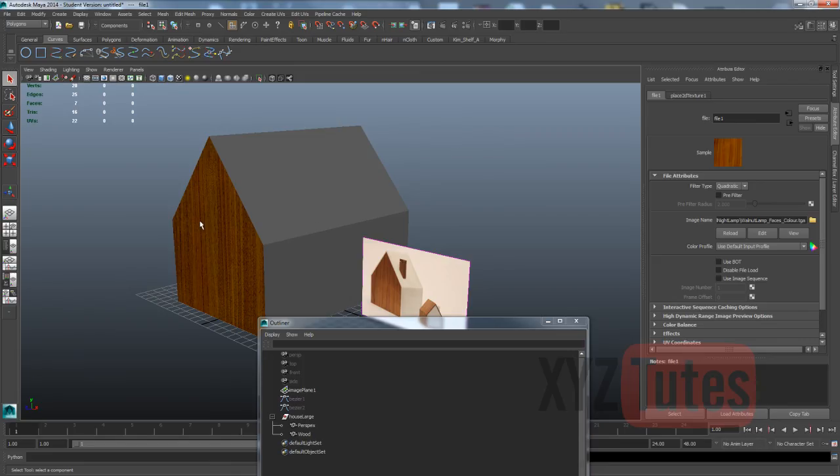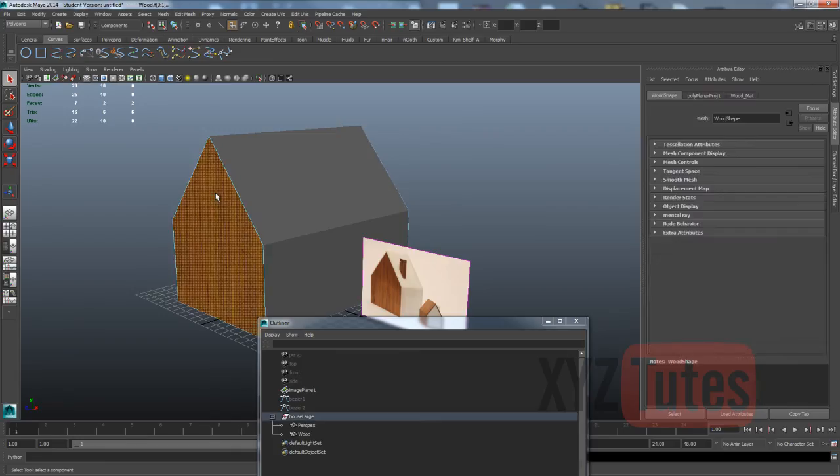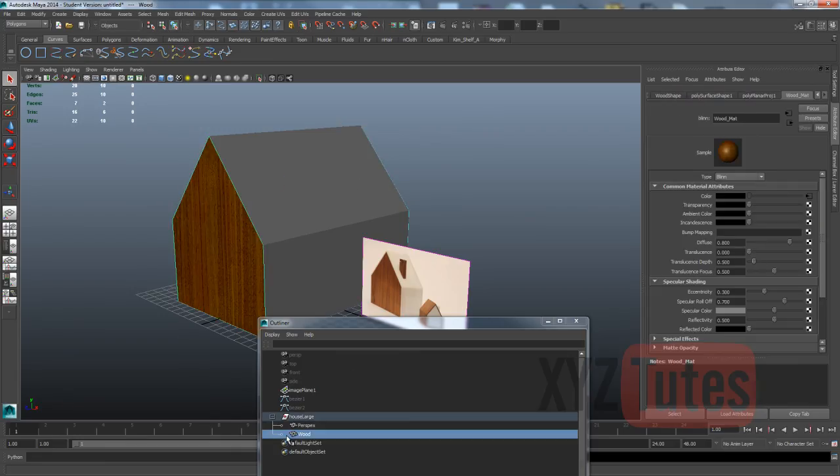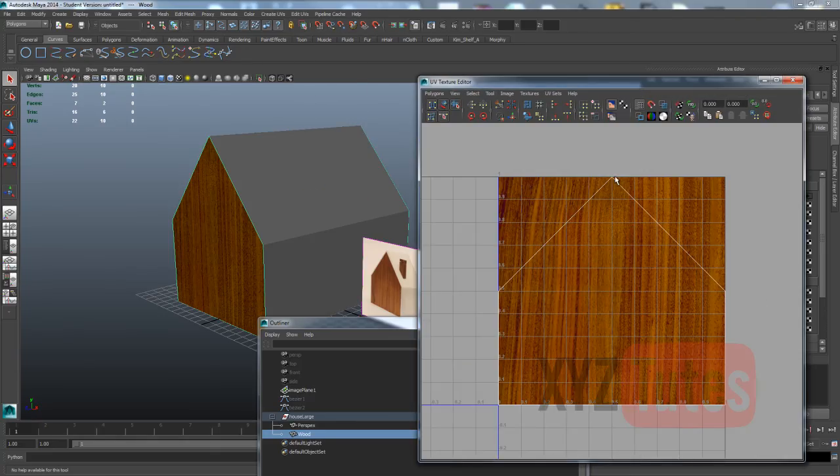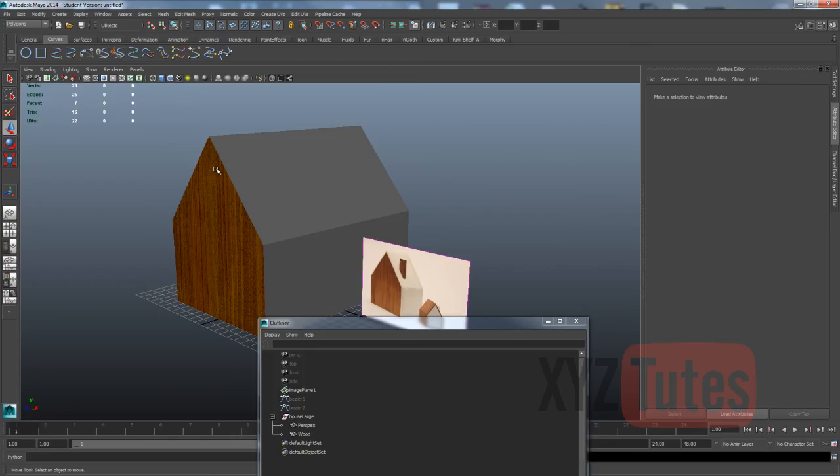And we can see how those texture coordinates are helping just by demonstration. I'll just select the wood object, go to Edit UVs and UV Texture Editor. And you can see that this face has been made to have coordinates so that it is matching this image in this way. So it could be slightly different, and we'll have a slightly different result. So that's all organized. Getting your coordinates ready for texturing is part of the modeling process.